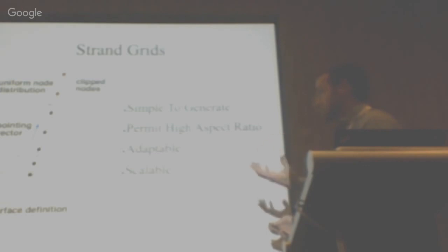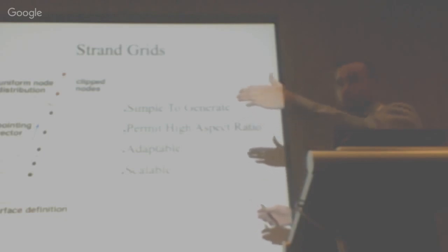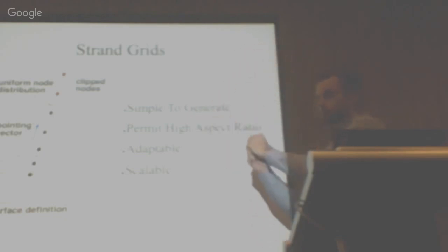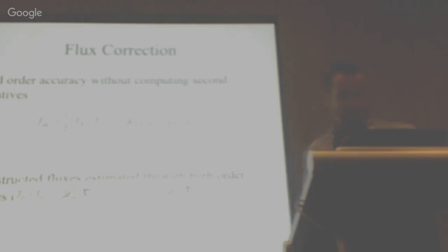One of the primary goals of this original code is to work with a helicopter blade. And as you can imagine, you need a moving mesh. And as that blade moves, you can just create a new one on the fly. Saves a tremendous amount of time in mesh generation. And these are also very scalable. If you can partition up your surface mesh, you basically already partitioned up your volume mesh as well. So we've run up to 2048 cores, probably pretty common in this room, obviously.